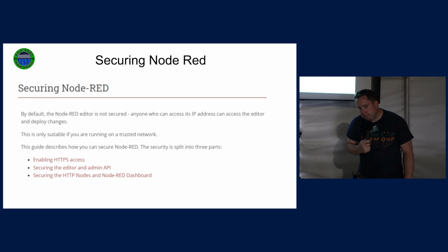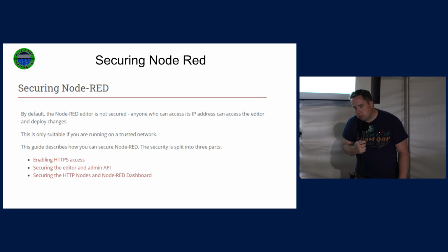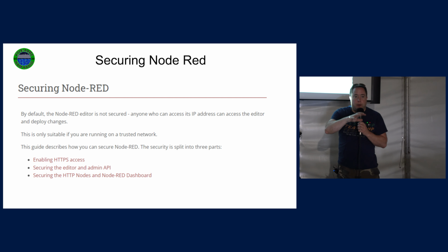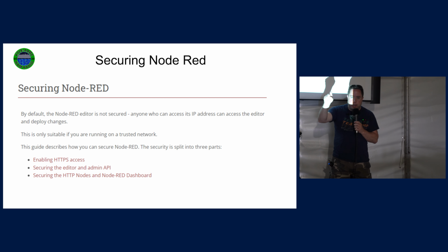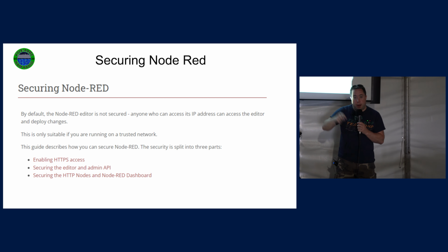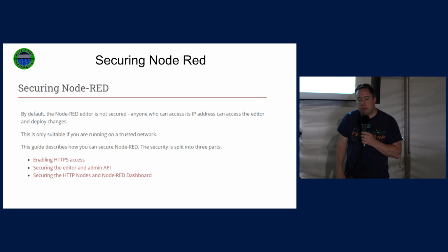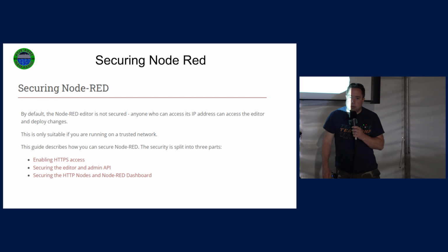When you build your flows and you have your dashboard, buttons and things, those aren't a separate web page published. They are part of where you did your workflow. Whenever you create your flow and all of your data flows into those dashboard nodes, that is found at your IP address of your Node-RED install, :1880/UI. If you have multiple dashboards, they're all at that same URL? Yes, pick the one you want.